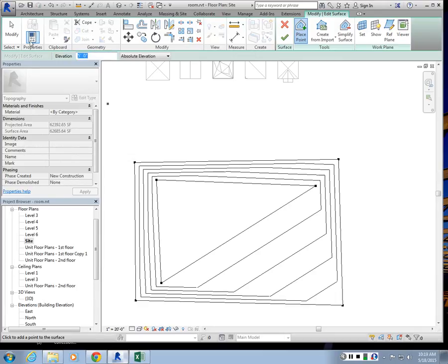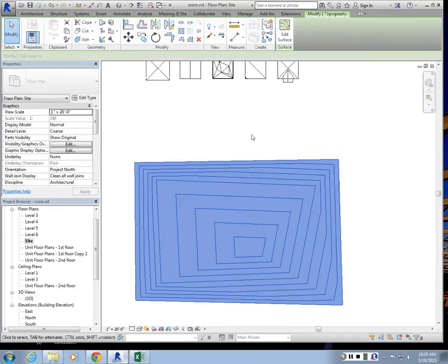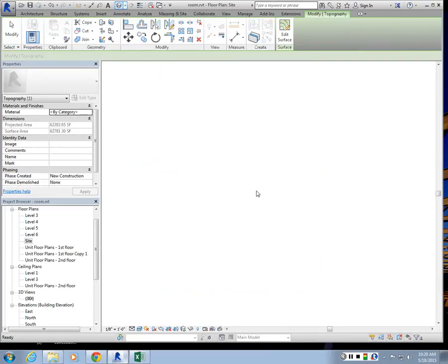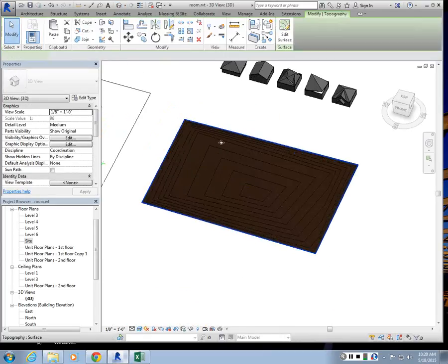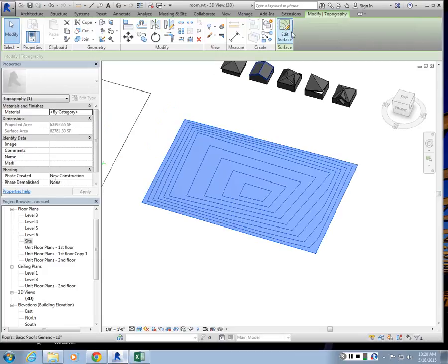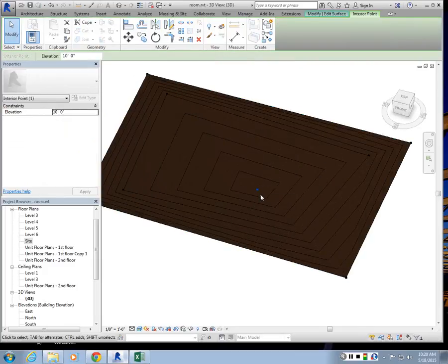And let's say we have another point at 10 feet. So I put it there. And I get a site. Once I'm done, I can hit check. And that's that topo actually, right? I create a simple thing. Then I can do edit surface as well. And if I want to change the spot elevation values of any of these points, I can select them again and change their elevation. So this may be, let's say, -5. So now it's going to go down, right?